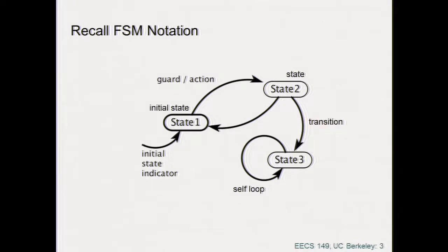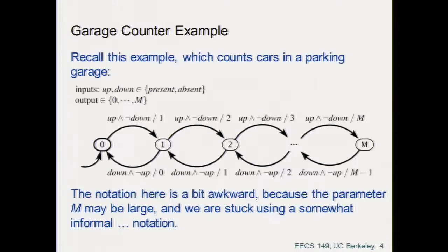We also have to give an initial state, so we have to indicate it somehow. I told you that in the finite state machine notation, you put a double circle to indicate where you start. Okay, and then of course you have a self-loop, which means that under a particular set of conditions, you stay in the same state. So you do an action, and the action is stay there, right? Since it is a transition, staying there in this model means that during that transition you can output something. So you keep on looping, but maybe that something changes and is the output during this loop.